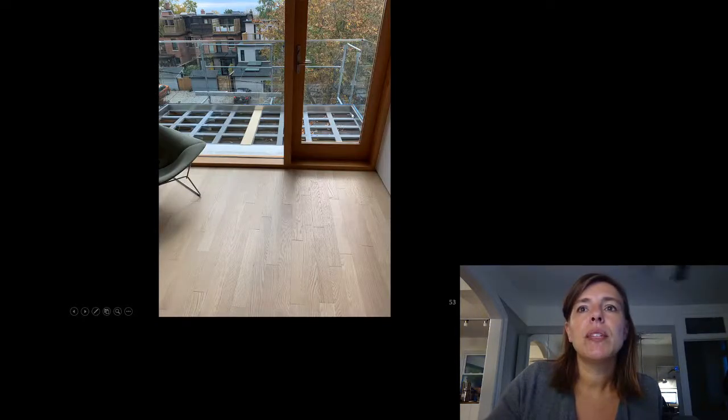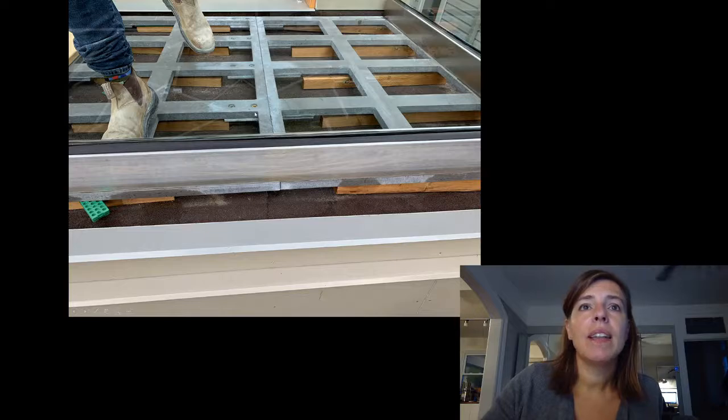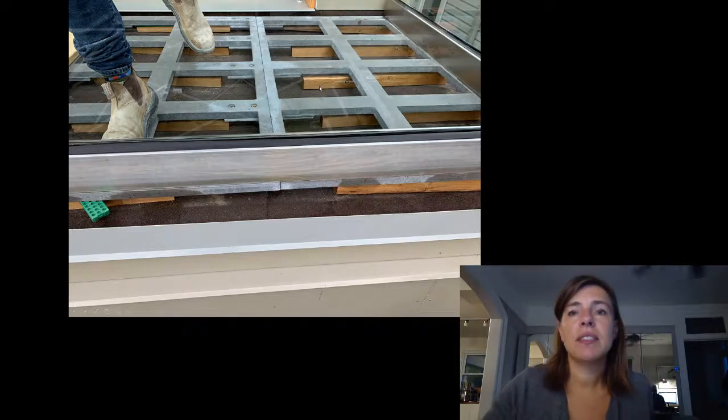It looks like what they actually ended up doing was, rather than drilling two of them, they brought the plates already welded to the underside of these ones, so they only had to connect it once. And so you can see here they've got the shoe detail and the glass guard going in, and they're getting ready to put their decking on top of it. So you can see these ones were welded to it, and then these ones were screwed down.